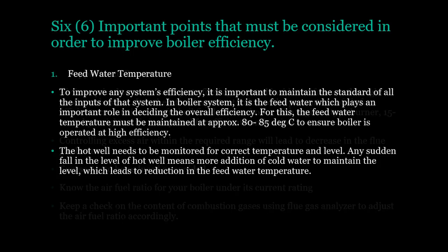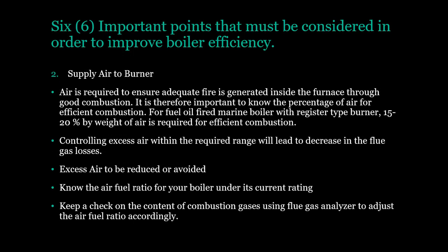Supply air to burner. Air is required to ensure adequate fire is generated inside the furnace through good combustion. It is therefore important to know the percentage of air for efficient combustion. For a fuel oil-fired marine boiler with register type burner, 15 to 20% by weight of air is required for efficient combustion. Controlling excess air within the required range will lead to decrease in the flue gas losses.